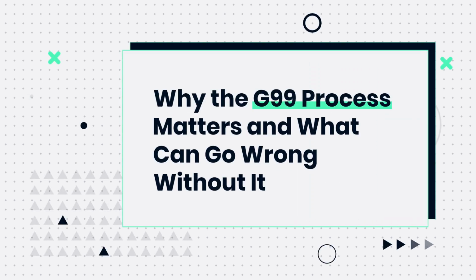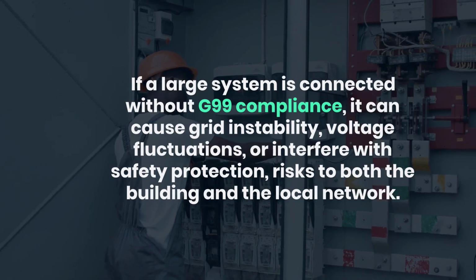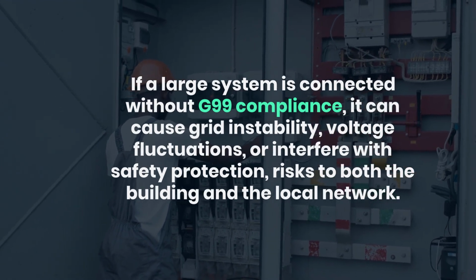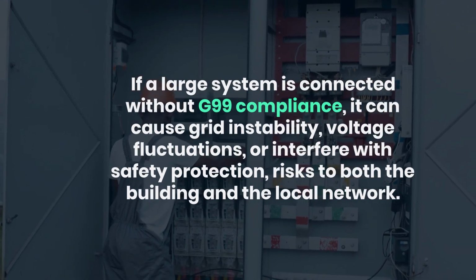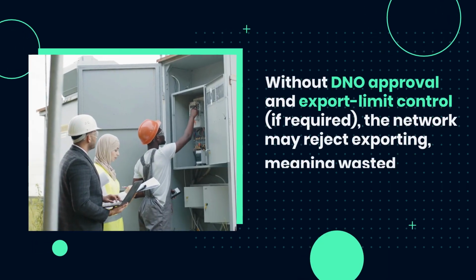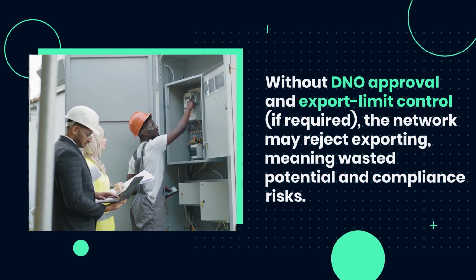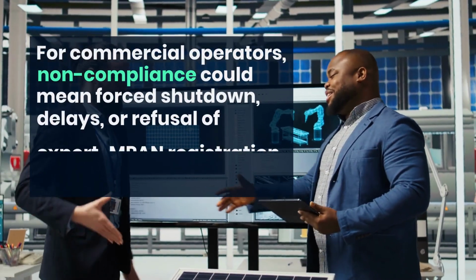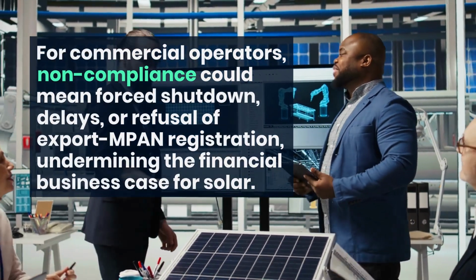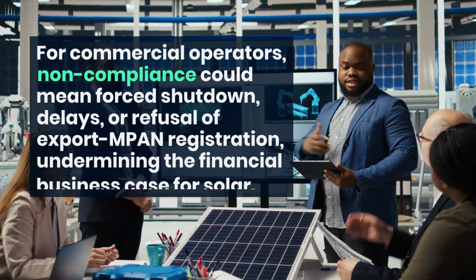Why the G99 process matters and what can go wrong without it. If a large system is connected without G99 compliance, it can cause grid instability, voltage fluctuations, or interfere with safety protection, risks to both the building and the local network. Without DNO approval and export limit control, if required, the network may reject exporting, meaning wasted potential and compliance risks. For commercial operators, non-compliance could mean forced shutdown, delays, or refusal of export MPAN registration, undermining the financial business case for solar.